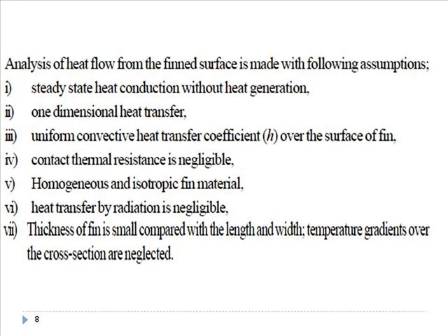First, steady state heat conduction without internal heat generation, one-dimensional heat transfer, uniform convective heat transfer coefficient over the fin surface, contact thermal resistance is negligible, homogeneous and isotropic fin material, heat transfer by radiation is negligible, and the thickness of the fin is very small compared to the length and width, so the temperature gradient over the cross section is negligible.